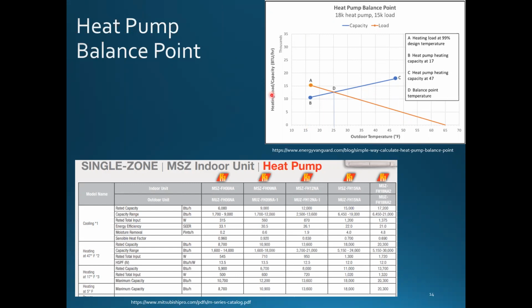The key here is that we know what the capacity of the heat pump is. They give you some kind of a balance point diagram and tell me what the quote supplemental heat is. What are they doing? Electric heater in there? Is it just going to switch over to the gas-fired furnace or boiler to do the work? They just need to kind of let you know.